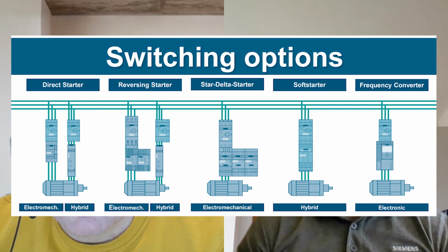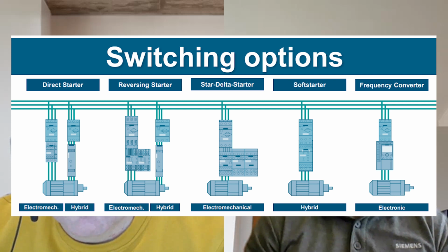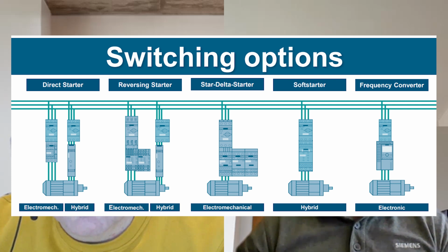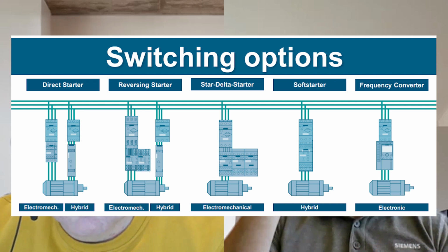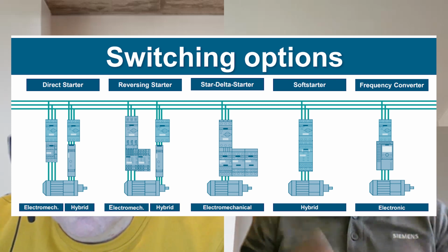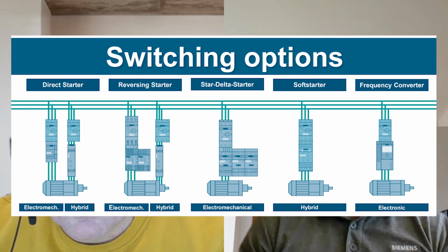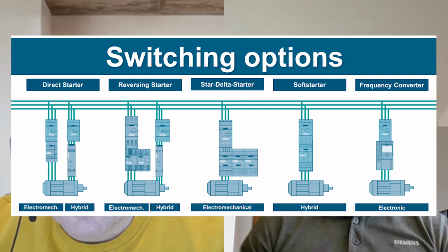And then we have the soft starters. Soft starters work through a voltage ramp. You have a starting voltage of, say, 200 volts, and then you set a potentiometer on the front of the device, which takes you up to the full line voltage, so you're slowly ramping that voltage up. That's actually an electromechanical solution, and it produces a lower starting current and a lower starting torque than the other three methods I just mentioned. And then the final one is the variable speed drive, the VSD solution.